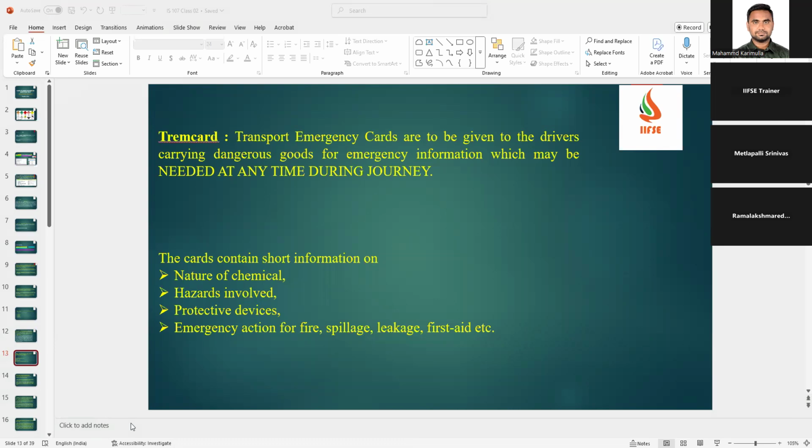Okay, sir. Sometimes we dispose of used oil, like synthetic and mineral oil. For used oil, we get a doubt about what we need to fill here, like what the hazards are. Should we write flammable? So, I mean, the nature of the used oil. The properties will not change much, because whenever we take it out of the equipment, it basically degrades in quality, but definitely it will burn. You can write only the flammable nature. You can't write that it is inflammable or less hazardous.